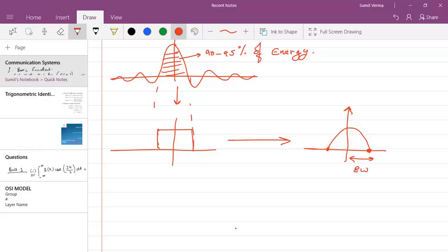Now it can be transmitted through a wired channel. Still we cannot transmit it through a wireless channel because it has a zero frequency component, so the antenna height required would be infinite. We'll need to modulate it before we are ready to transmit it through a wireless channel. This process is called band limiting, and we achieve it by using a low pass filter of suitable cutoff frequency.